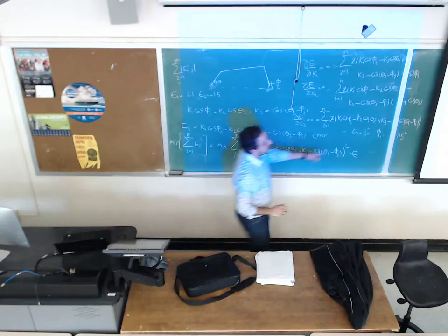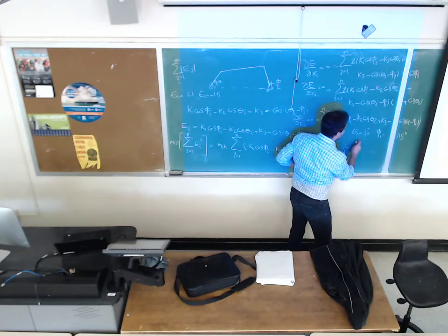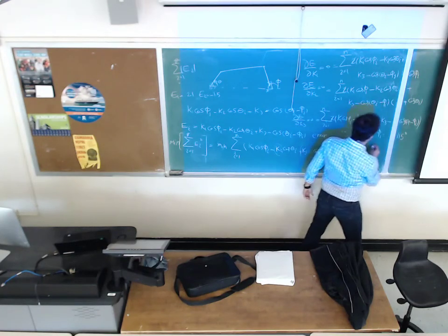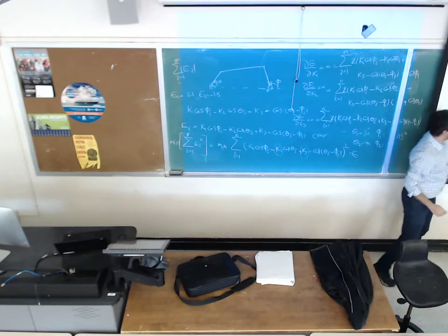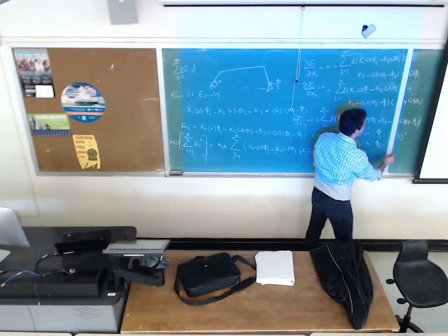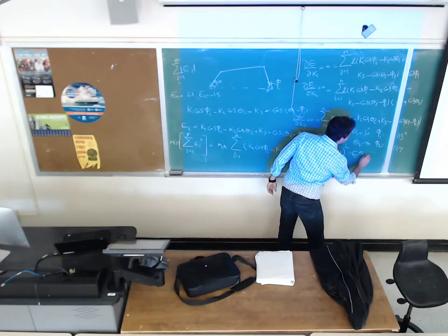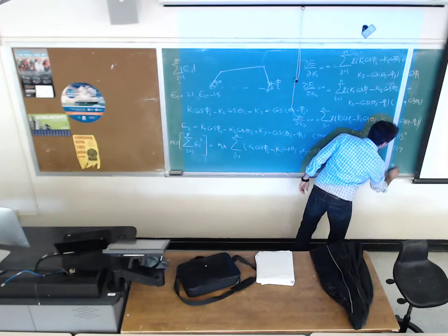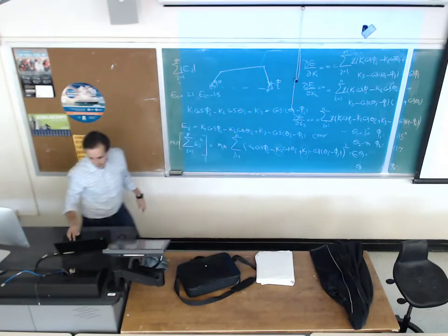we are given theta 1,2. If we are given theta 1,2, I can find theta 2. Theta 2 is theta 1 plus theta 1,2, which is 40. Phi 2 would be phi 1 plus phi 1,2, 115 plus 12, 127. Find theta 3, theta 4 up to theta 8, and phi 8. So you have 8 precision points in this case.